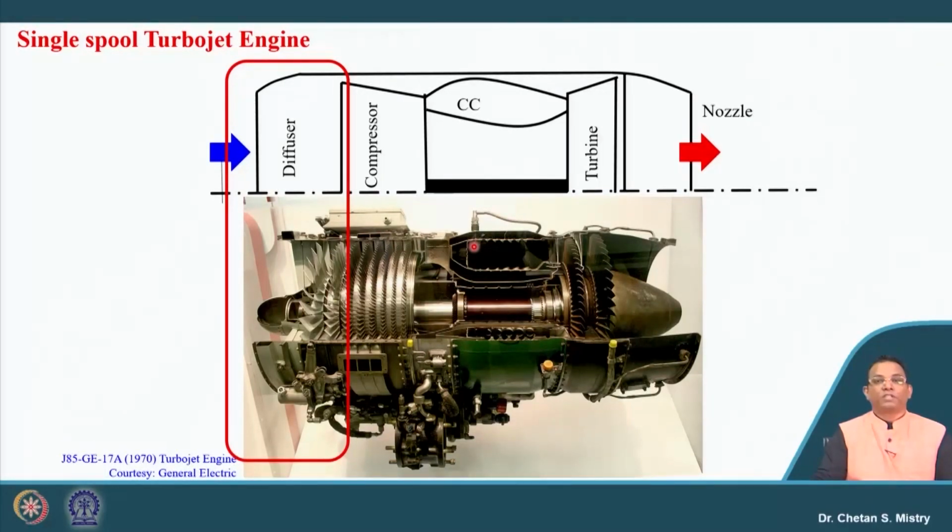So for that purpose, starters are installed at the location here, which will rotate this engine at a particular speed. Once it achieves that speed, it will start automatically for the suction of my air, and you will have the rise of pressure, injection of fuel and burning, and the turbine will start rotating. Once it reaches that speed, that starter will automatically get disconnected. So do not get confused about how the engine will be started.